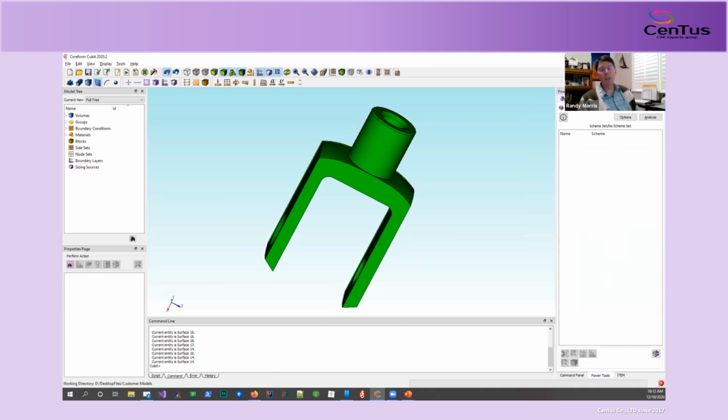I could narrow this down to specific volumes. In this case, we only have one volume. I'm going to click Analyze, and it tells me something interesting right off the bat. It tells me volume 1 is not meshable. It says no scheme set. That means Cubit can't automatically put a hex mesh on this model.